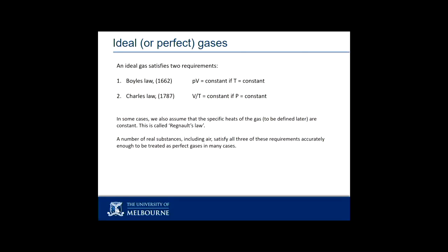The important thing is how far away from the critical properties you are of that gas. Which is to say, when you are super hot or super compressed, generally you're getting close to breaking the rules. If you're getting close to condensing out of vapor phase, out of gaseous phase into liquid phase, generally you're not an ideal gas. And that's the rule that gets broken with water. And when we're at super high pressure, that's a rule that gets broken with air or nitrogen or argon or